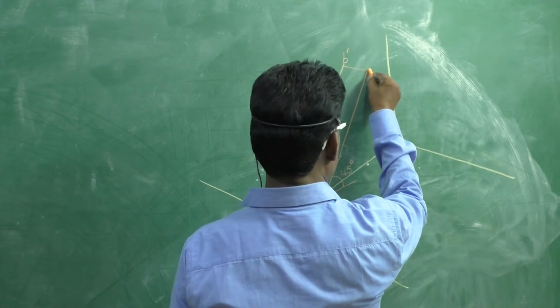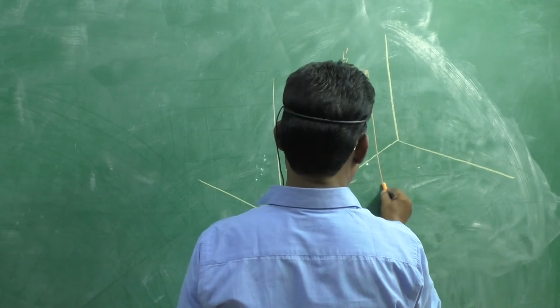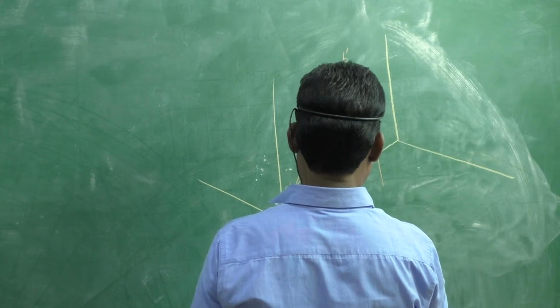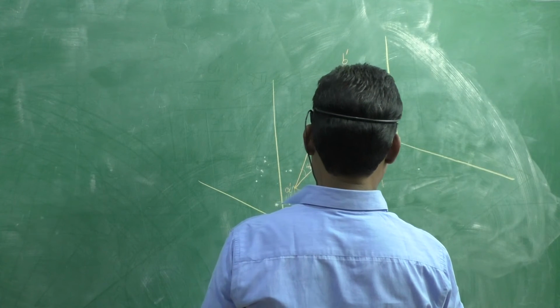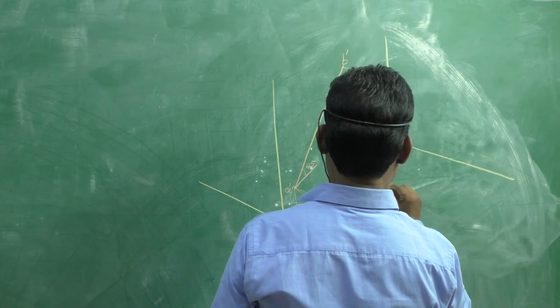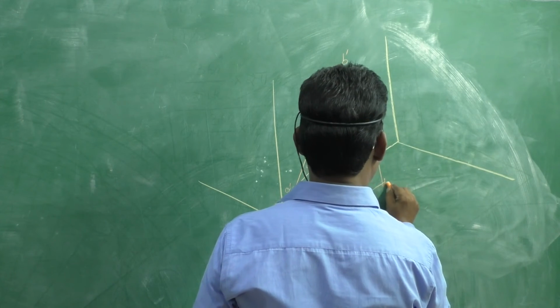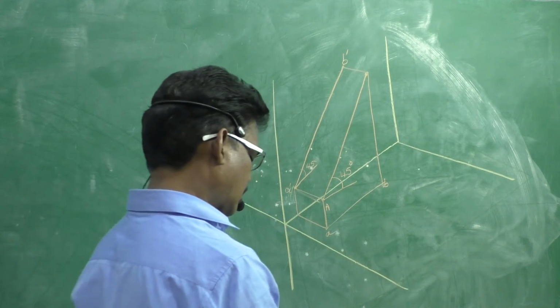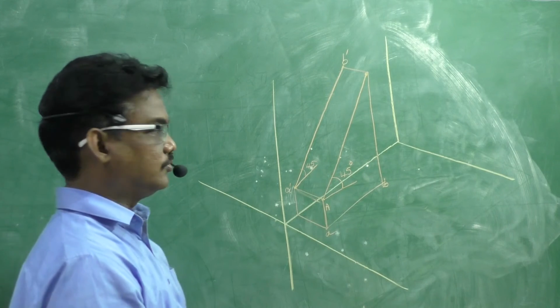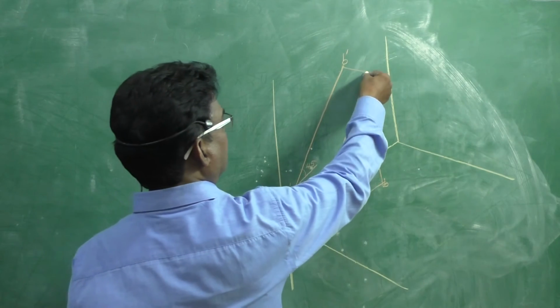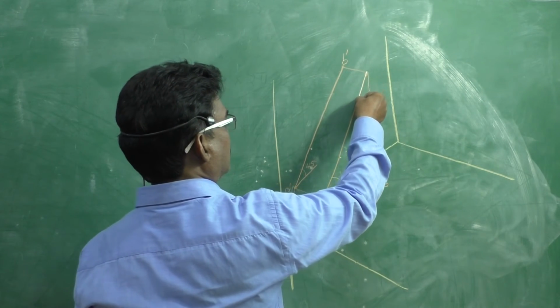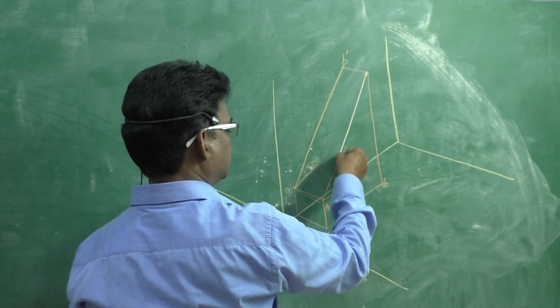Right. Now come to the top view. In the top view we need to project downwards, and we need to project A also. And if you draw it, this is the top view. This is A and this is B. Right. Now we will darken the respective views. Okay, the given line. This is the line we considered.